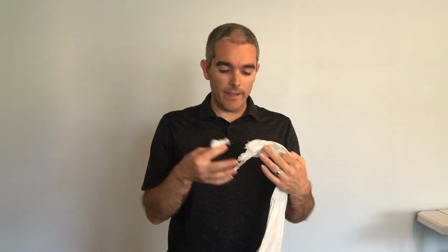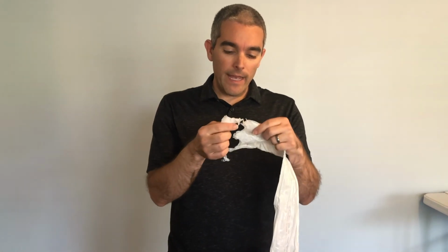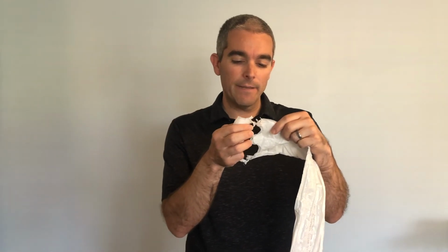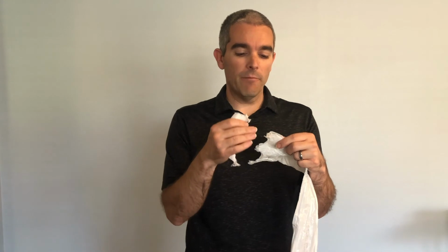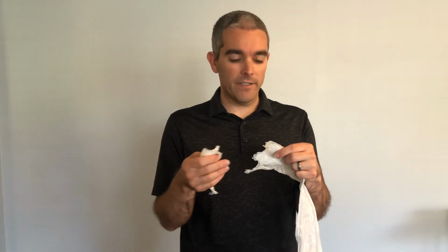The most common question I get about this demonstration is, why do we not check yield at the net section? I just want you to think about this for a second. It's not that at the net section we don't experience yielding. If you go back to that video and look at it, you'll see that as I pulled, we first got stretch at that net section, and then we got fracture. And so we have to remember back to our stress-strain curve diagram. We're always going to experience yielding before fracture.